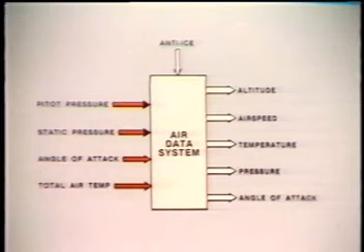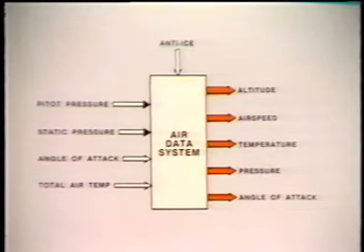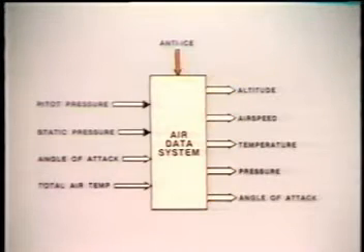Using inputs of pitot pressure, static pressure, angle of attack, and total air temperature, the air data system provides information on altitude, airspeed, temperature, pressure, and angle of attack. Finally, there are anti-ice heaters that prevent icing on probes and sensors.